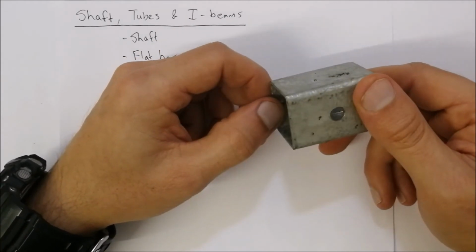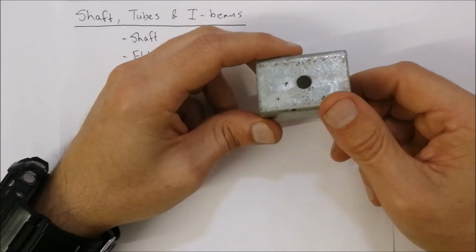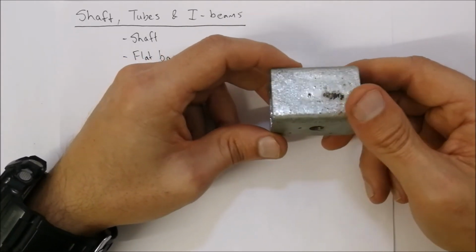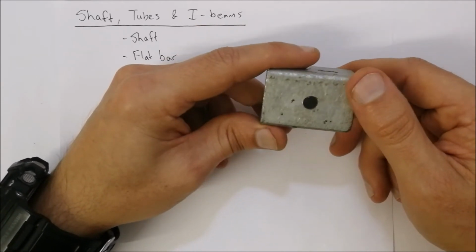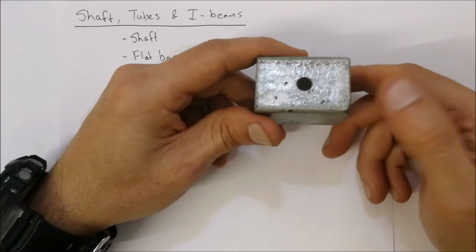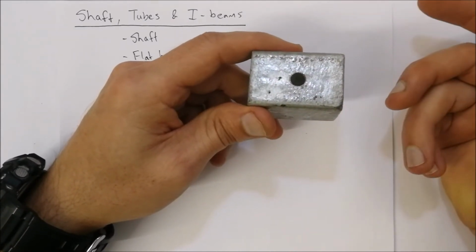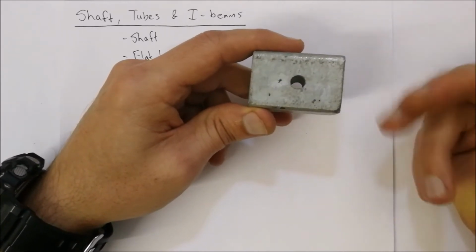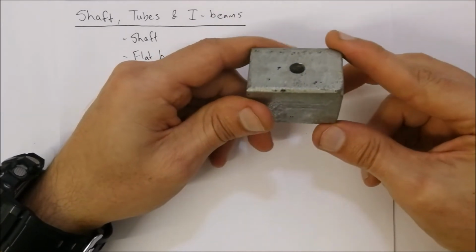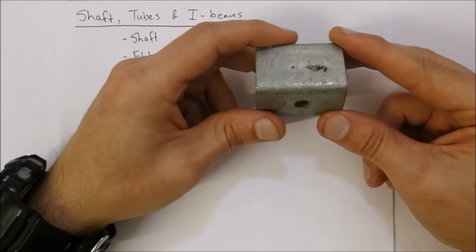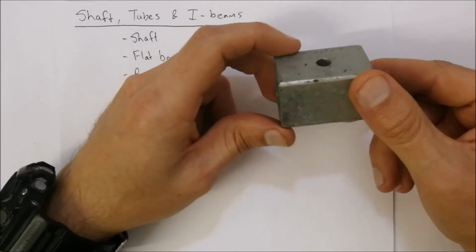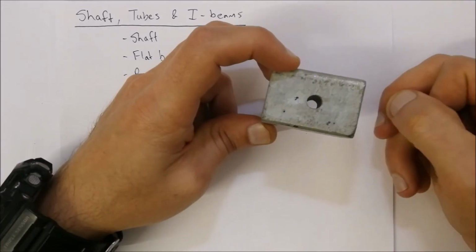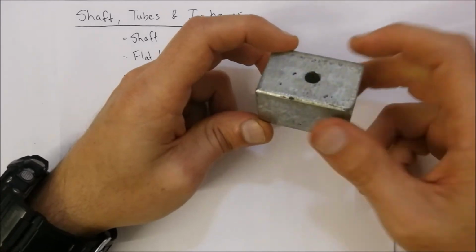Otherwise you would have to take your mild steel and paint it, and that's essentially how your vehicles are done in terms of the bodywork, they are painted and therefore protected from corrosion. Because remember, corrosion needs water, it needs iron, and you need oxygen. So if the water and oxygen is taken away from the layer, it will prevent corrosion from happening. Okay, so you would often find that cars might actually rust, and it is because often the paint might have chipped, might be a stone chip or so, and in that specific place will start rusting.